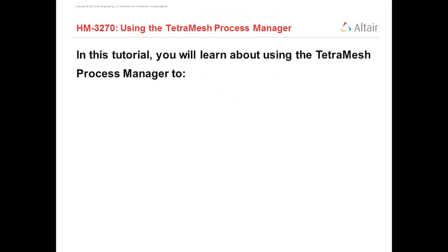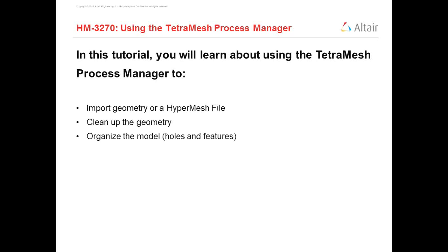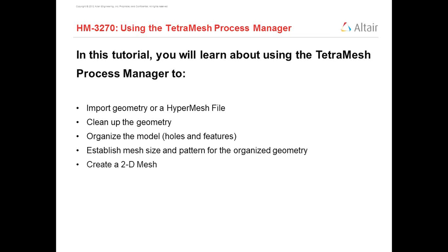In this tutorial we will learn about using the TetraMesh Process Manager to import the geometry or HyperMesh file, clean up the geometry, organize the model, holes and features, establish a mesh size and pattern for the organized geometry, create a 2D mesh, clean up the 2D mesh, and create a 3D tetra mesh. So we will see this.